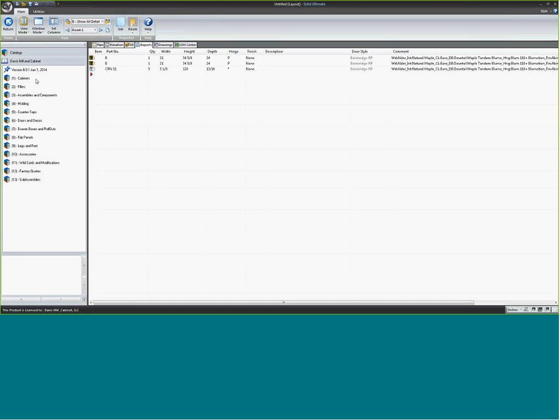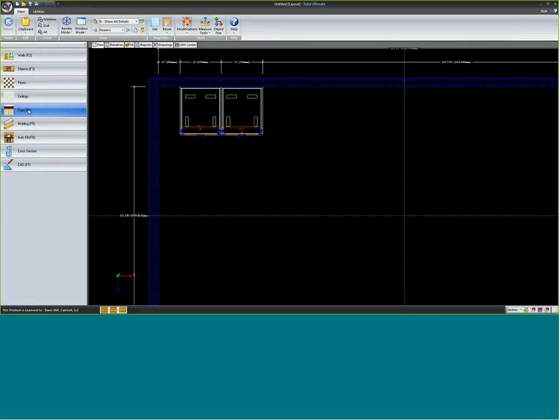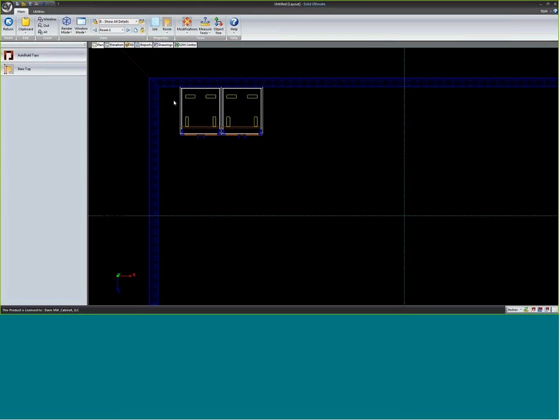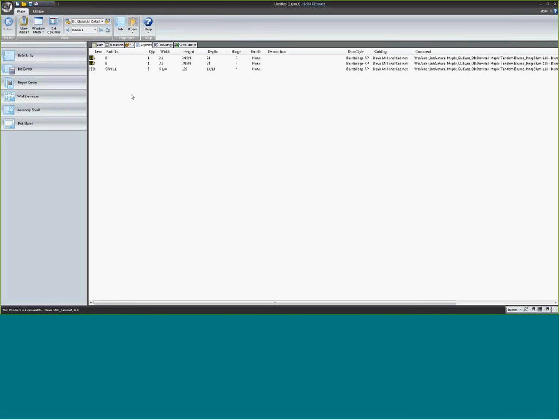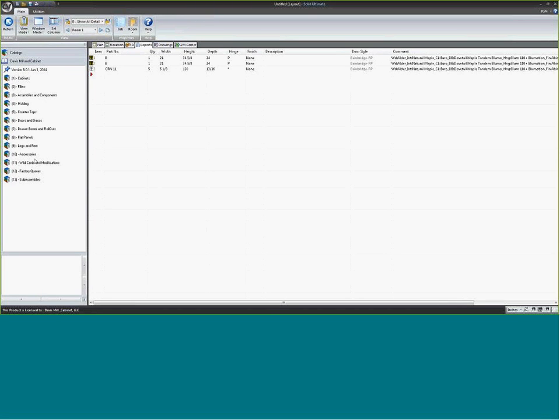So that's molding. Caps are the same sort of way. In Cabinet Vision, if I use this countertops button, I can place countertops out on my cabinets. Again, that's only for rendering. This is for tops that are granite or solid surface, marble, plastic laminate, whatever you're putting on for countertops on the job, just for rendering. If it's a countertop that we're actually building, which in most cases are just standard wood tops, veneer tops, or butcher block tops, those are all entered also as ghost items.